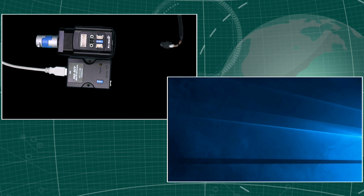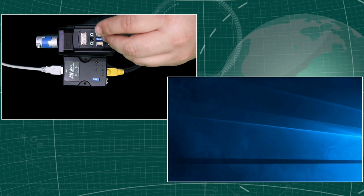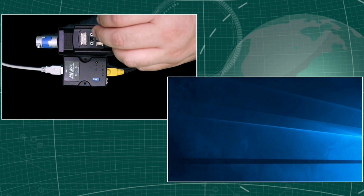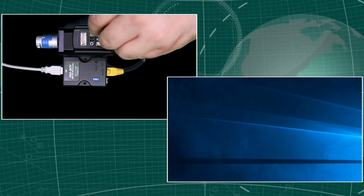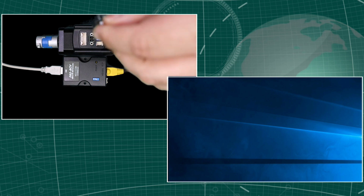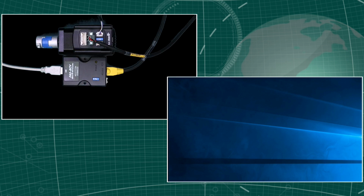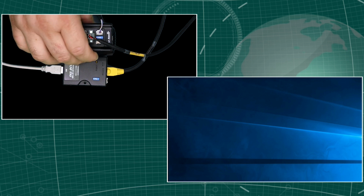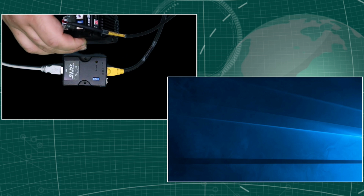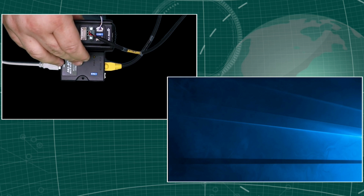First of all, we will make a connection between the converter and the controller. We have our RS485 signal, and the other thing we need is a power supply. Here we have 24 volts, and now you can see already that the slave is shown with number 0.